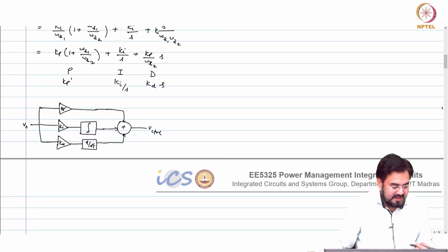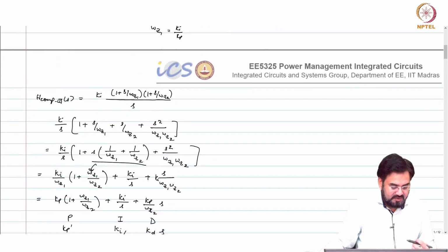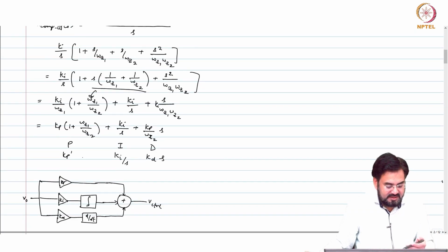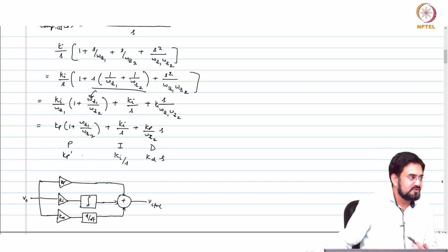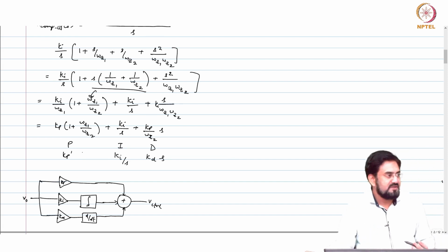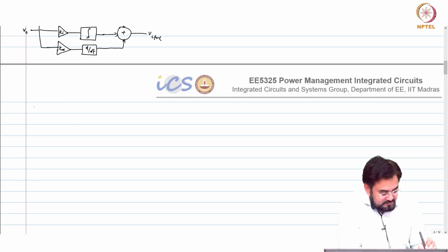So, basically the gain of the integrator and differentiator will be nothing but the coefficients Ki and Kd, and you add all the 3 and you can independently tune all the 3, but ultimately what we are doing here, by changing Ki, Kd or Kp, you are simply changing the gain and location of your 0, so that you can get enough phase margin to make it stable.